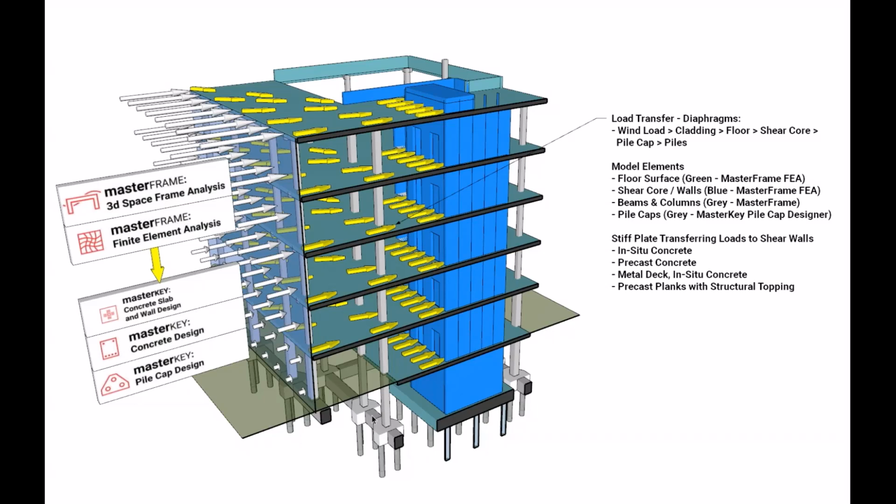And then we've also got, shown in grey, the pile caps, which will have their design carried out in the MasterKey pile cap designer. I'll note that the pile cap designer goes up to 9 piles. So in this case, we would need to model a shear core pile cap as an FE surface and then design that separately. But back to the load transfer.